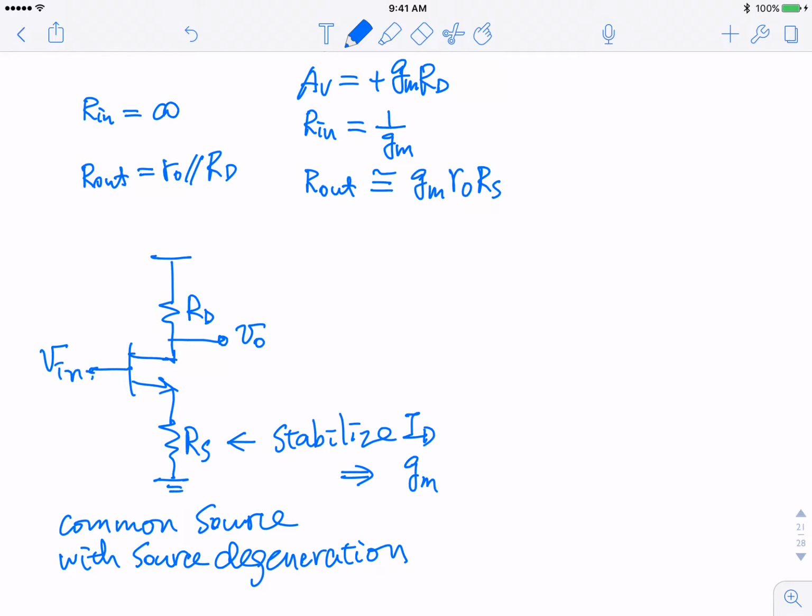A very simple intuitive explanation for that is, this circuit sets up a current ID, right? And ID sets up all the small signal parameters, basically gm. ID is equal to the voltage drop here, VGS, okay? So imagine if ID somehow is influenced by temperature, as in the example of the lab we want you to investigate. Let's say temperature changes, ID changes. Let's say ID, for example, tries to increase.